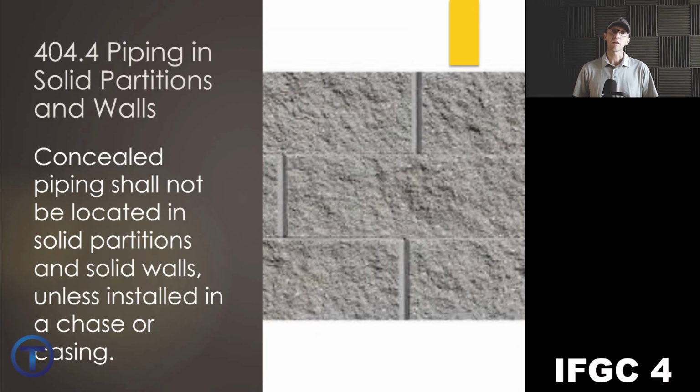What about piping in solid walls? Let's say we're dealing with a commercial building and they're putting up cinder block walls. They're going to fill that with grout. What about that? Piping in solid partitions and walls, it says, concealed piping shall not be located in partitions and solid walls unless installed in a chase or casing. It can't be just directly installed, grouted in, buried in a concrete wall. So a chase is like an open space that we can even get to if we need to. And casing is a protective space around the pipe.